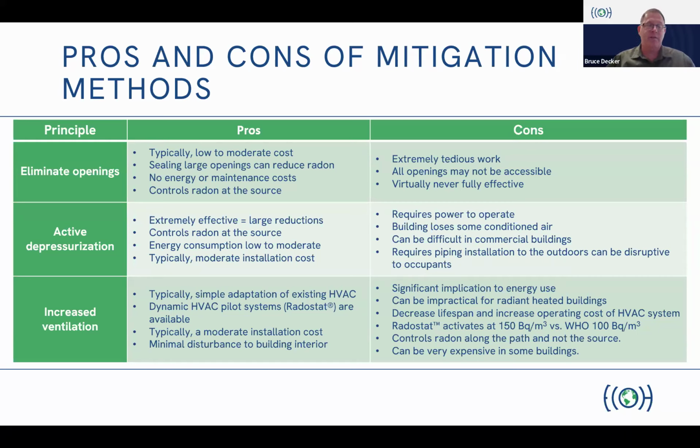A lot of the openings aren't available. There's a lot of basement areas where the drywall wall's up. You can't access the areas that really need to be sealed. And it's virtually never, ever affected by itself. We always seal openings when we do a mitigation because that makes the mitigation more effective. And it's just a smart thing to do. But trying to eliminate radon from entering the building through just pure construction practices and sealing, I can guarantee you right now, it's probably never, ever going to work.